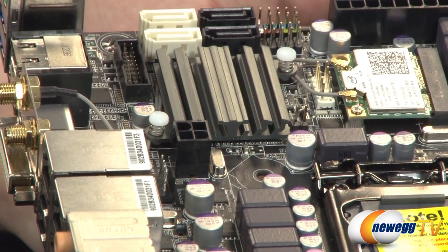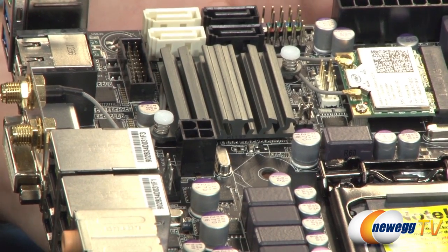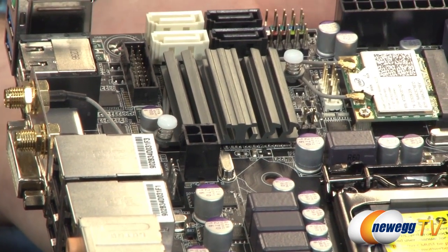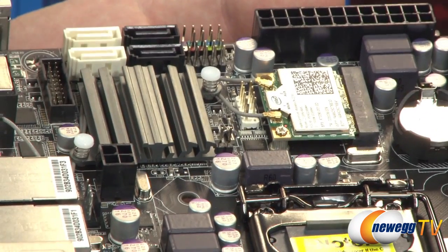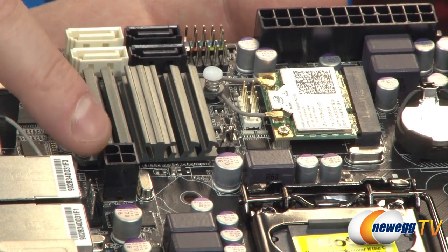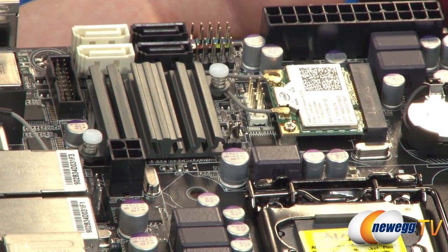So when you're choosing your power supply for your system, let's say you've already chosen your motherboard, just make sure that you have the 24-pin, which you're pretty much always going to have. And then for your CPU power, make sure you've got at least the 4-pin. And some motherboards that have an 8-pin, you can actually just plug a 4-pin in and it will work just fine as long as you're not overclocking.